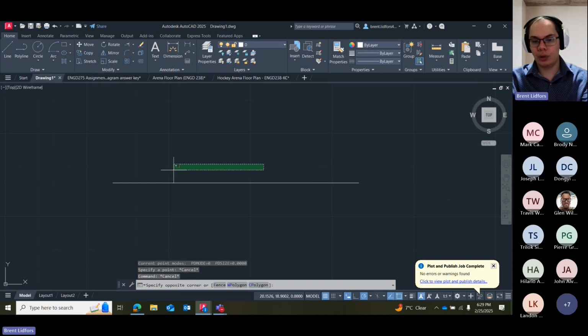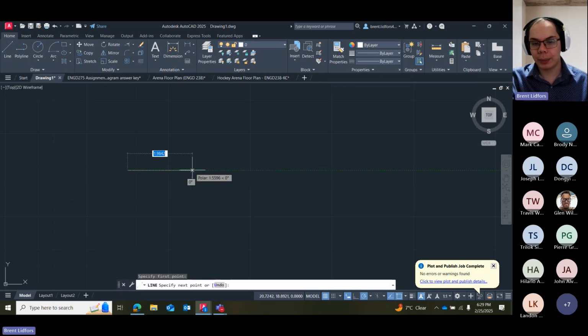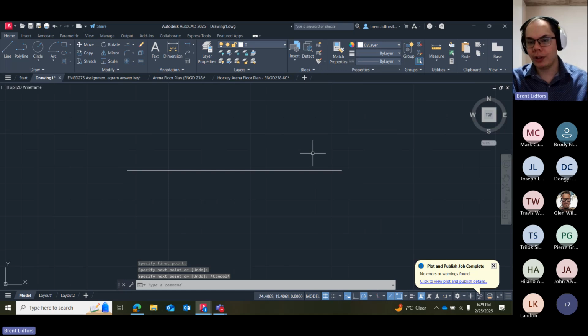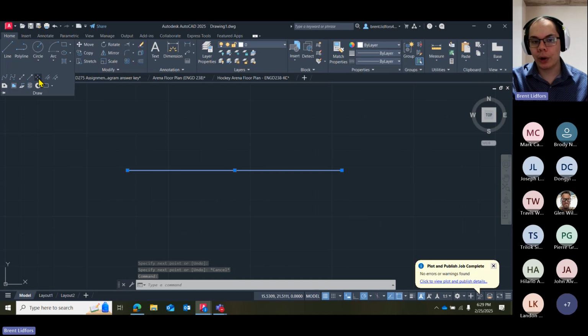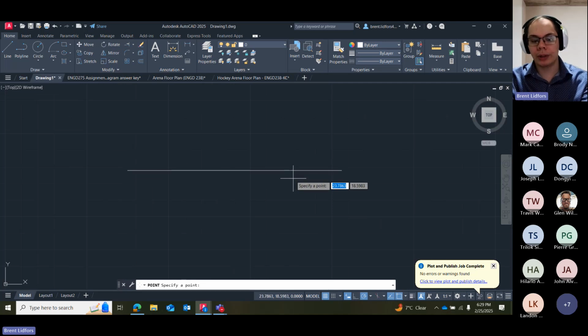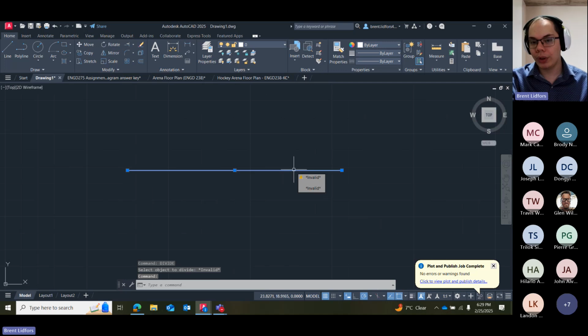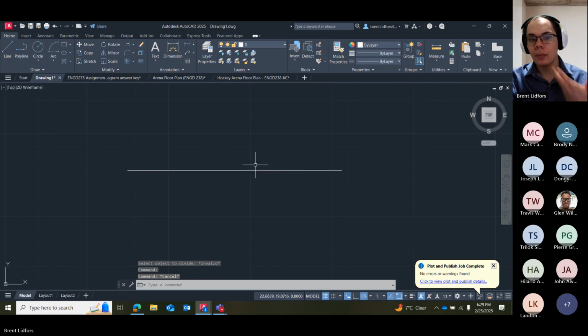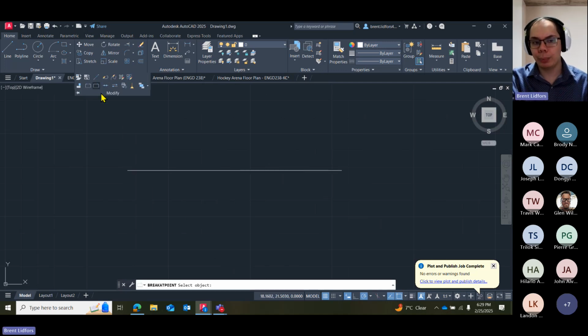So if I were trying to take a line segment and turn it into 7 divisions of that line segment, I could go ahead and try to put points along here or use the divide command to put points along that line. Or I can just use break and break every 2 units, let's say.